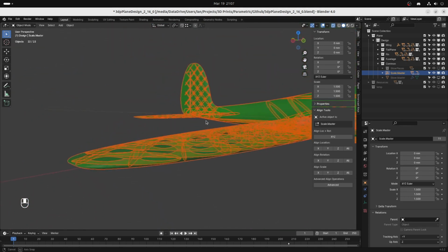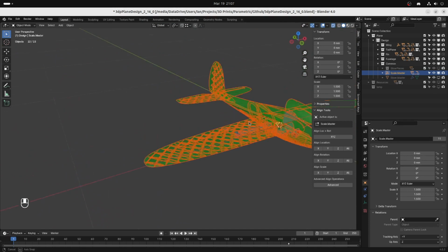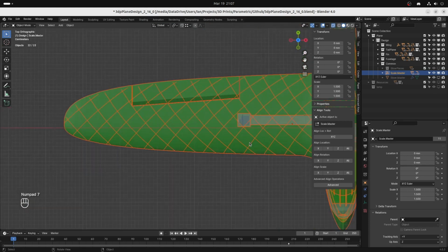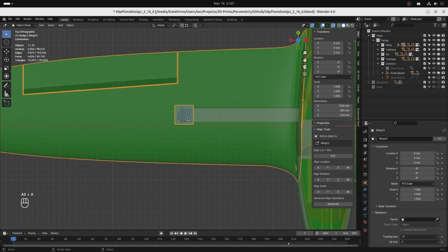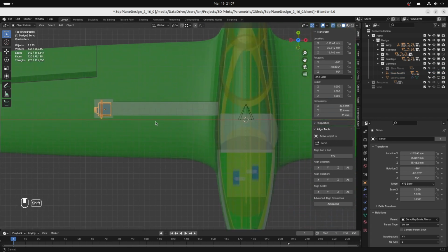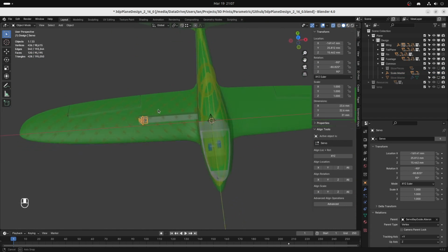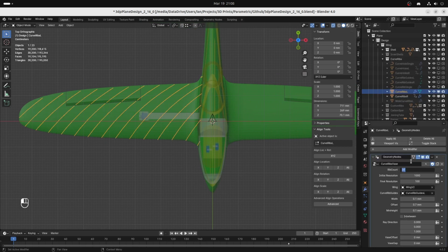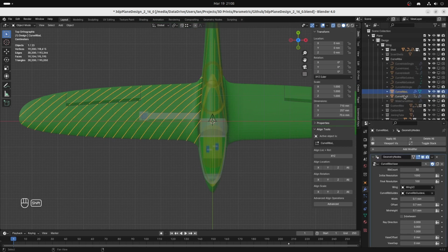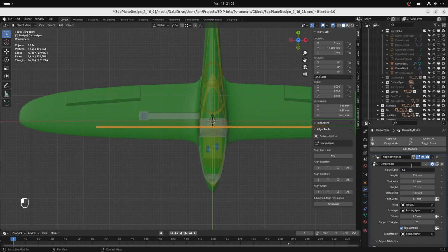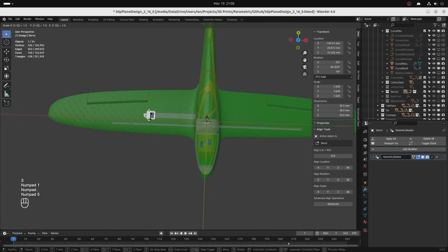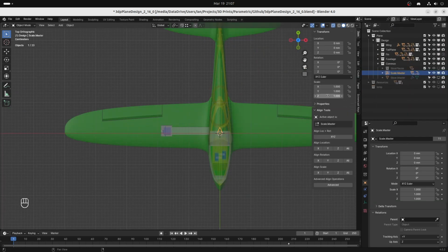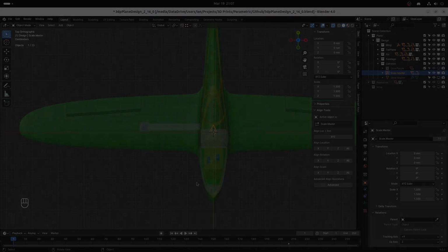For example, the gap between the ribs and the wing surface should stay the same. The servos and the servo base sizes and things like that. Of course, when changing the size of the aircraft by more than a small amount, there are likely to be some design changes required. For example, I may choose to manually increase the number of ribs in the wing. Perhaps I'll want to increase the diameter of the carbon spar, or choose bigger servos. I'm hoping this should make it easier to create a small prototype of a design and then test it and then scale it up to a bigger size.